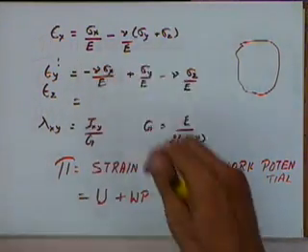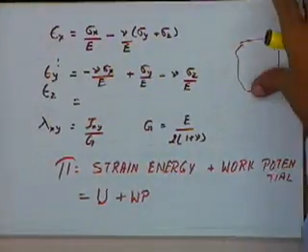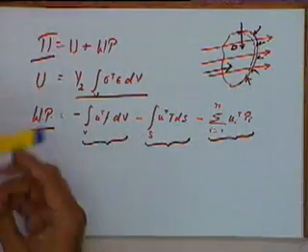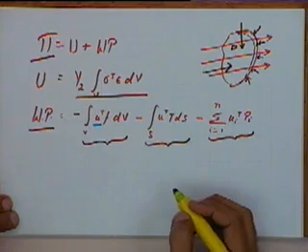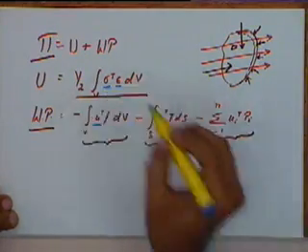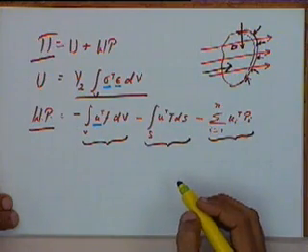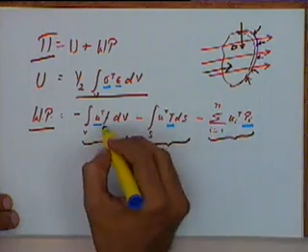Once I know the stresses, I can get the potential energy from this equation. Because if I know U, which is the deformations, I can find epsilon. If I know epsilon, I can find sigma. And I know the loading T and PI's and the F's.